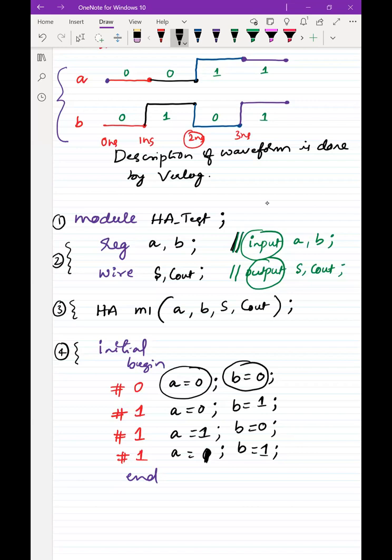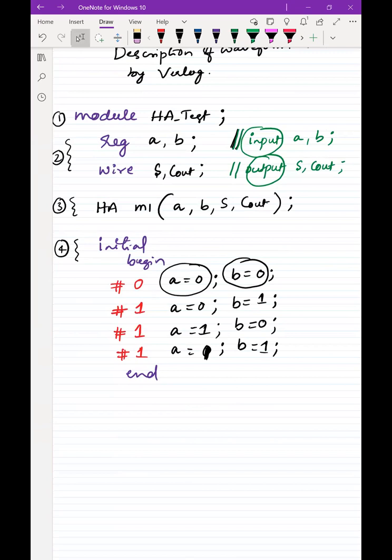Okay. But in addition to this waveform declaration, we have to write necessary information above this one. Another important thing is that once we have described the waveform, we need to write how do we look at this waveform? It is in the form of a textual format, right? Text format, I want to look at the output. So for output purpose, I'm going to use another initial statement. Initial. I'm going to write a statement called $monitor. This is the keyword.